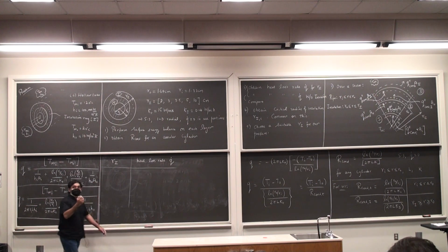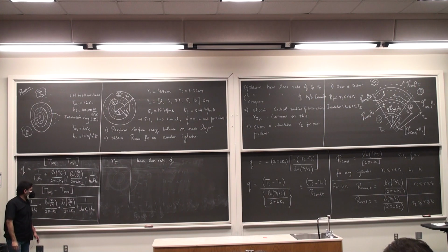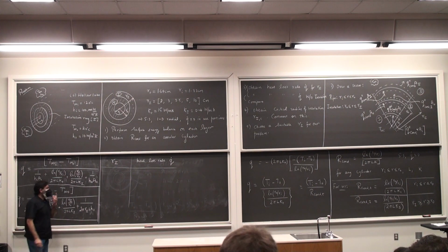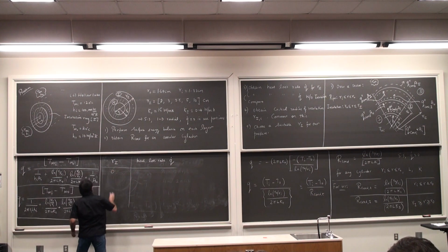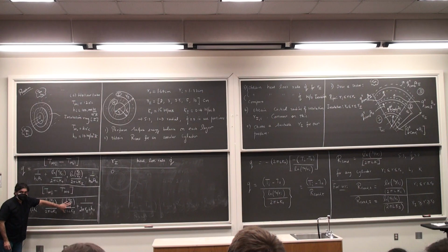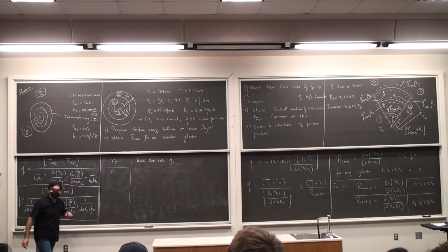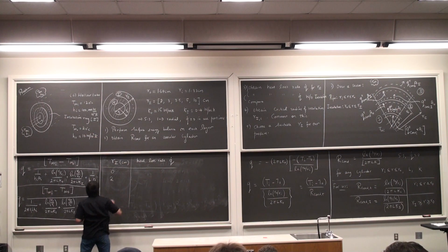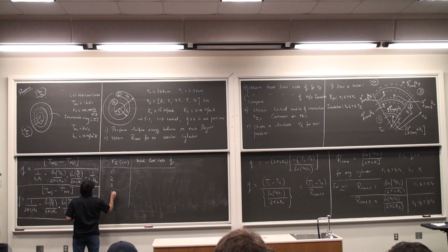I start off with Ri as 0, okay? So which typically means that I cannot use this term here. So when Ri is 0, I do not have that ring at all. So Ri of 0, which means that you ignore this particular term. Does this make sense to everybody? There is no insulation ring, so why are you including its resistance? That's about it. Okay? Then I have 2 centimeters, then 3, 3.5, 5 and 10.